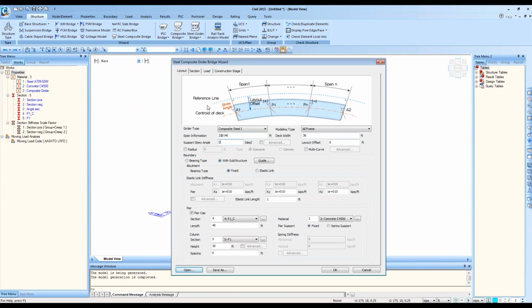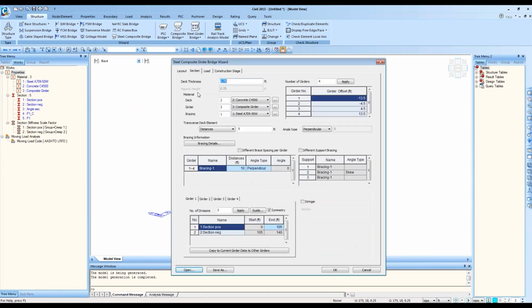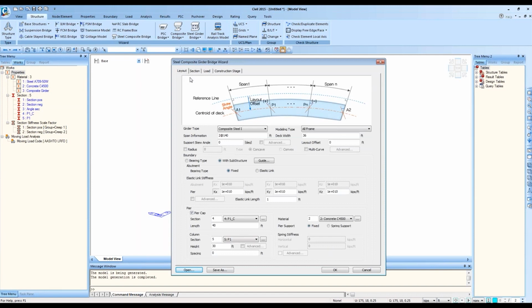So basically, the girder information, if you had a chance to look at the wizard, you will notice the girder information for girder 1, 2, 3, 4. No matter whether your structure is curved or skewed, or has different length for each girder, you're going to notice that the end length for every girder is the same. Meaning regardless of your structure being skewed or curved, and each girder line having a different length, the girder length is indicated to be the same number in the section tab.